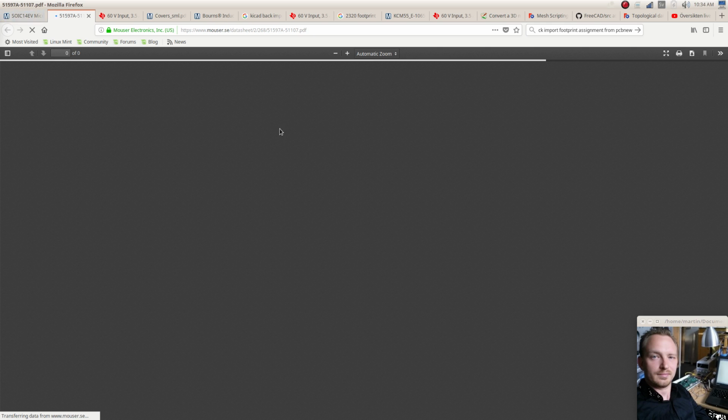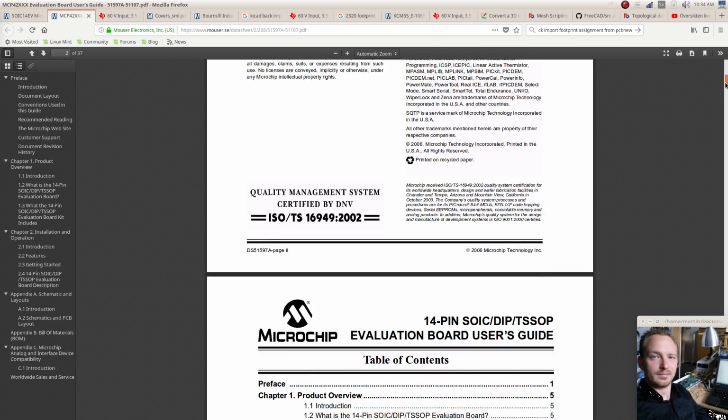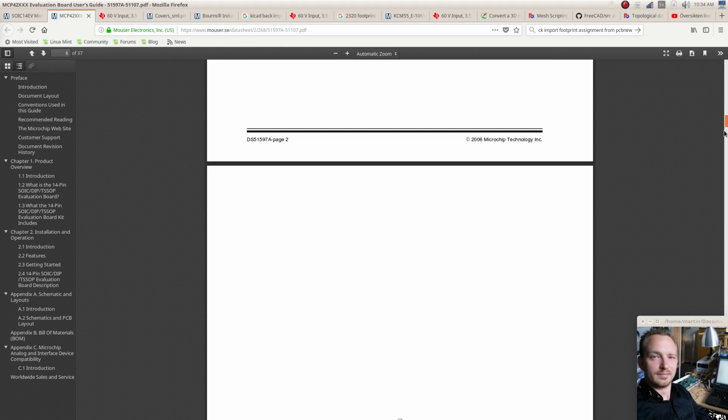So suppose I were going to use this particular chip in a design, and then it comes to assigning the footprint. Let's see if we can find a footprint for it first in the KiCad default template libraries, and then we're going to generate a footprint for it.